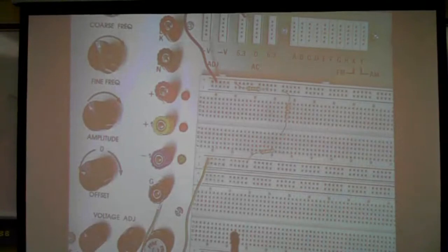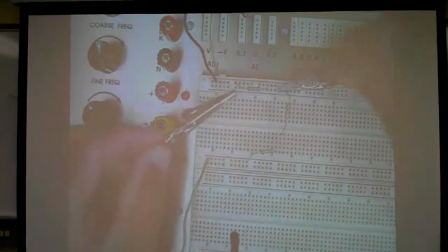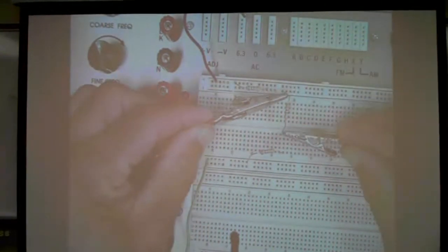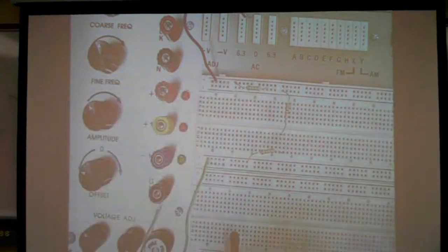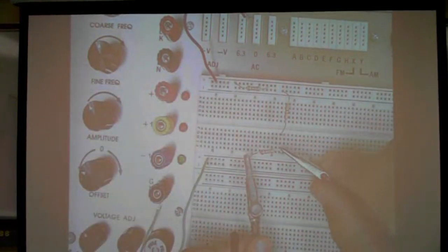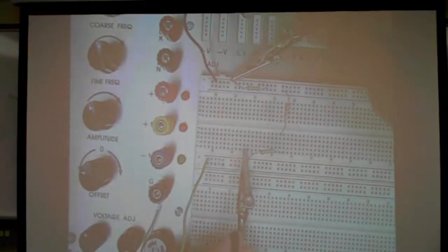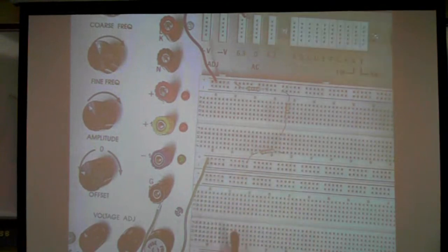Now in table 4-2, you're just going to take your voltmeter. You're going to measure across this resistor to get VAB. Then this resistor to get VBC. And then this resistor to get VCD. And you record those in the table. They also want you to get your supply voltage. So that would, of course, be my total voltage. So VS, then VAB, VBC, and so forth. And fill out those values for table 4-2.